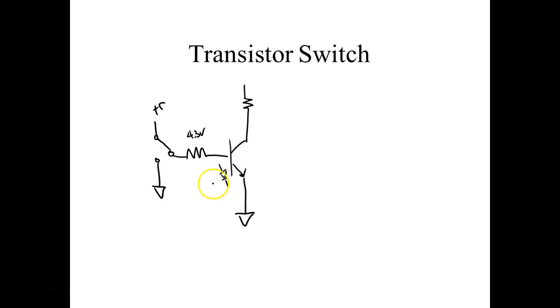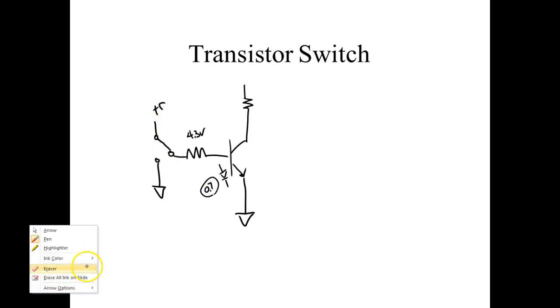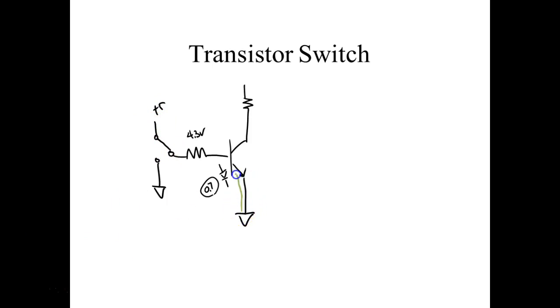Well, the diode, we talked about this a while ago. If this is a silicon diode, it's going to drop 0.7 volts. Kirchhoff's voltage law says the sums of the voltage drops in a series loop has to equal the applied voltage. If this guy right here is dropping 0.7, I put 5 volts up here. Here's my current path. Of course, it's going up the other way, but here's my current path. Comes up here, goes up through here, goes like that. So that's a little series loop, right? You understand? Kirchhoff's voltage law says it has to drop the applied voltage.